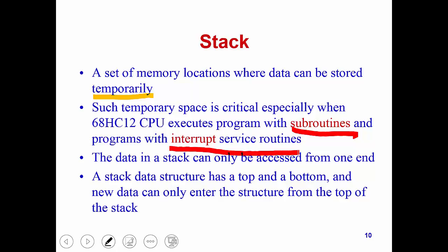Same idea when we come to interrupts. We do something sequentially, and our program is interrupted by some high priority event. So we stop what we're doing now and take care of that. But when you stop here, you should save the key values of registers somewhere, so when you come back, you can use them. Because if you don't save them, then when you go to take care of this high priority event, these key register values may be overwritten by some operation during the event. That's called an interrupt service routine.